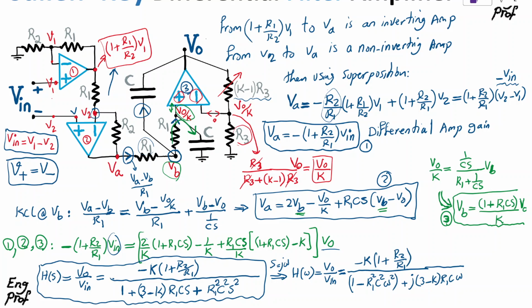So it's very interesting because this can effectively form a low-pass filter in which we can set the values of R1, C, and K properly to find the proper location of the pole for this low-pass filter, and therefore define the magnitude Bode plot exactly as we want.